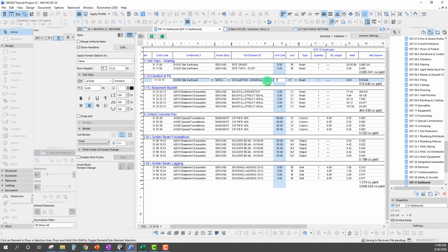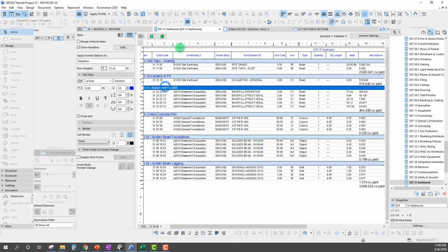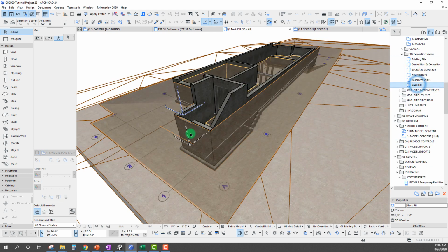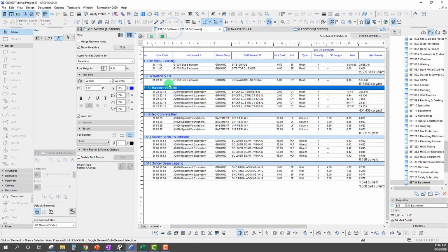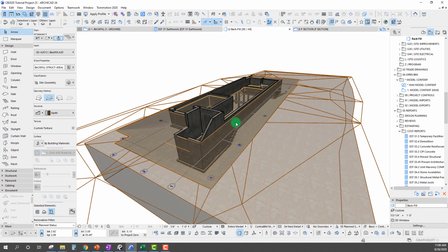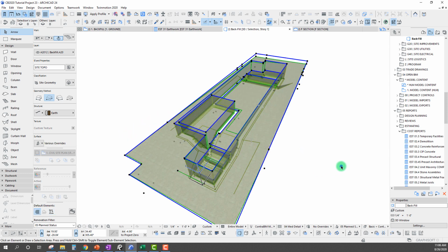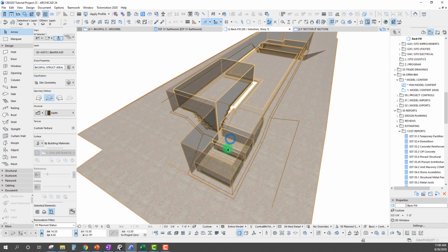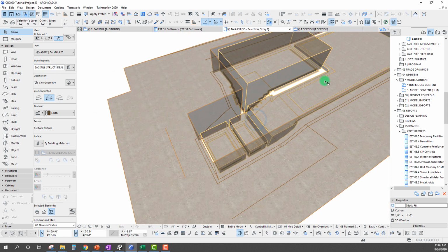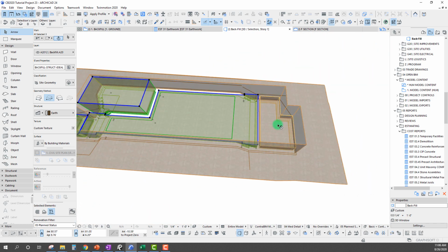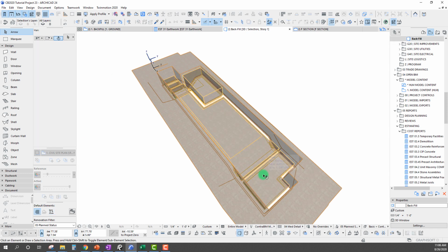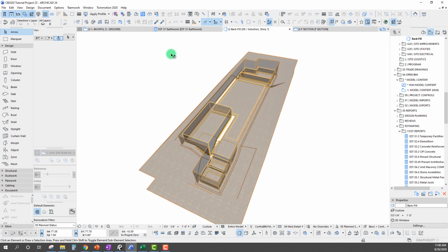We are just going to go with a general $5 a cubic yard to start. And then same thing with our basement backfill. We need to change up our view here as we're bouncing back and forth to be able to select all these. So let's grab them. We can isolate them here, and then you can really see that we have our backfill at our perimeter. We have internal backfill, which is really going to be like a structural backfill here because we have structural elements going in on top of it. So we have these structurals.